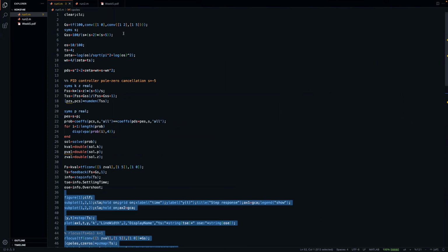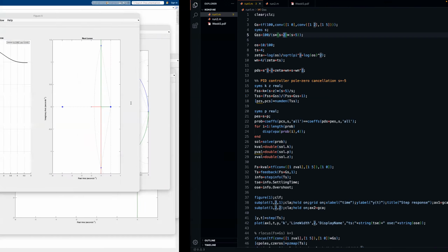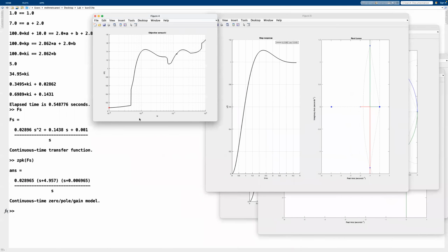Heating up the system changes the resistors and stuff like that, which changes the position of the poles by manipulating the whole model, because the parameters will change, the poles will move, and your pole zero cancellation will never be perfect. That's not possible. You can't have a system in the real world that has exactly a pole at 2.0000001. That's not possible. It will be something around 2, but not exactly 2. And that's the reason why pole zero cancellation, on the other hand, is also quite dangerous.